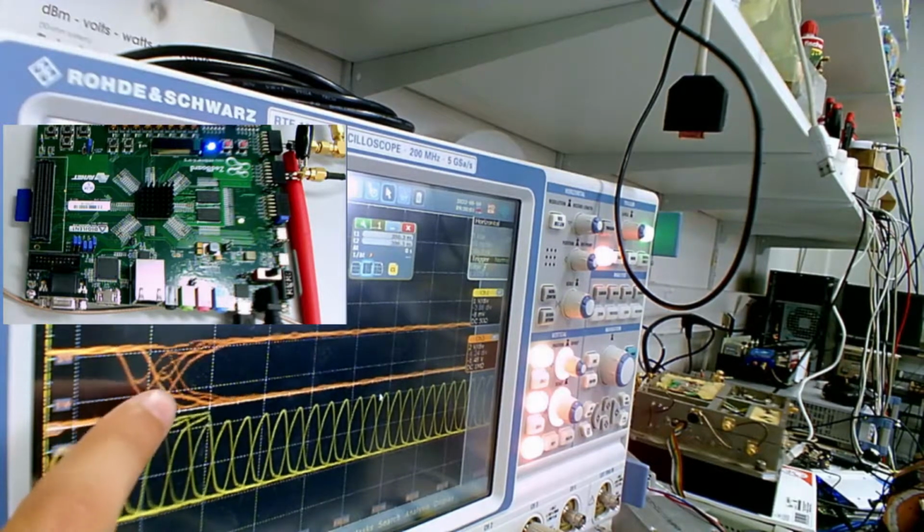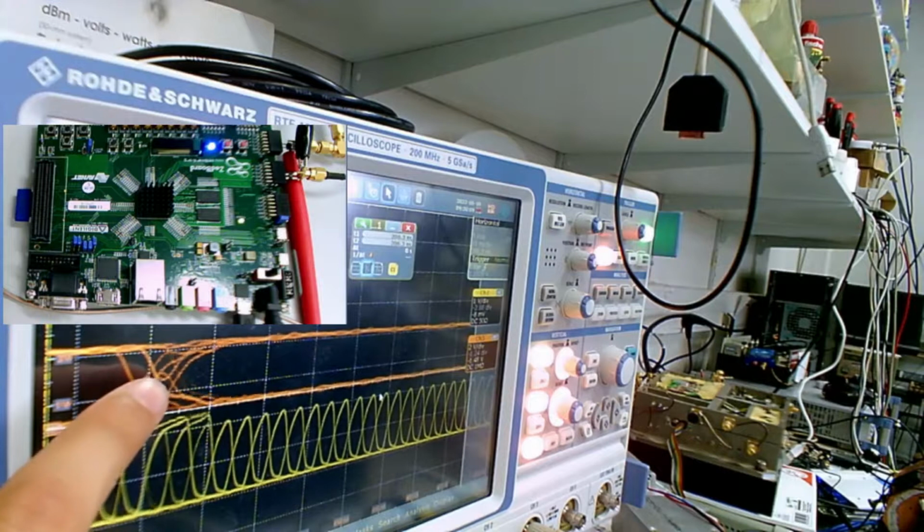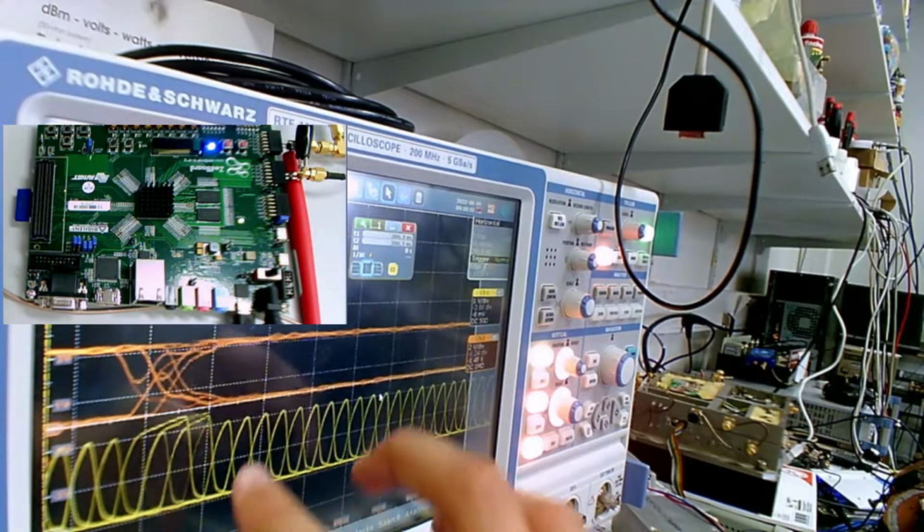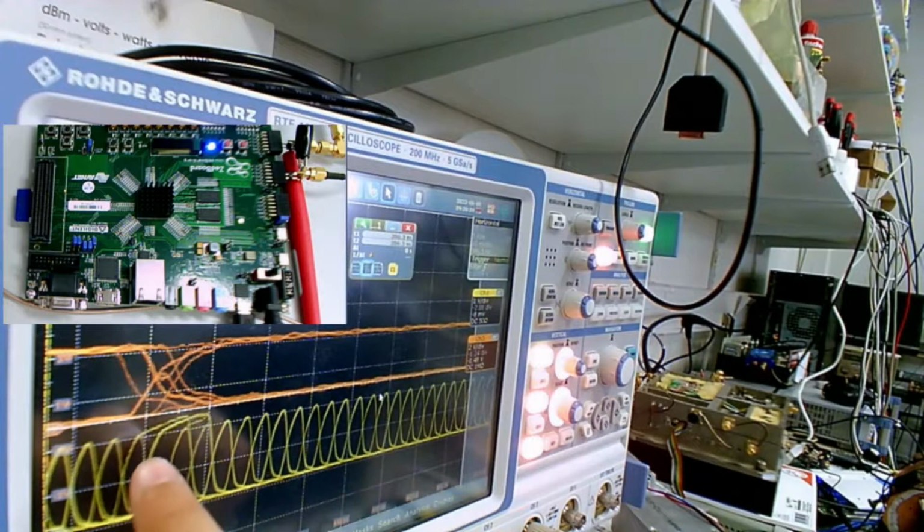There is some trouble with what we talked about earlier, the fact that we shift the signal twice, and so there is a small amount of time during which the pseudo-random number is not in a stable state. And so this is why you see this garbage. But what's most interesting is the fact that the modulated signal here can shift up to 4 different states.